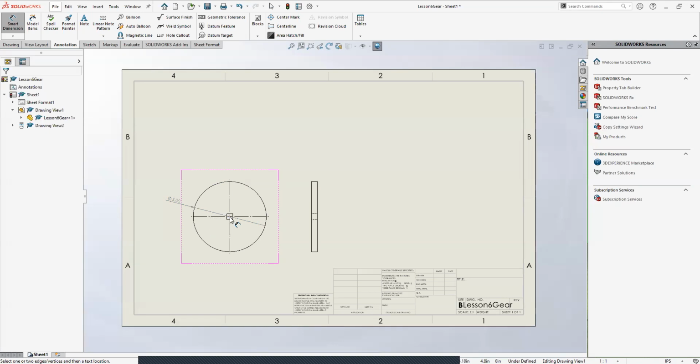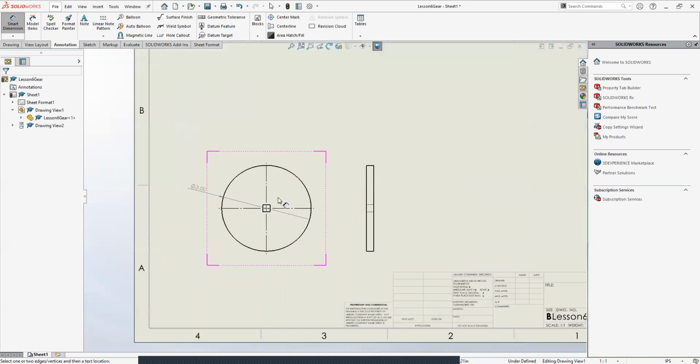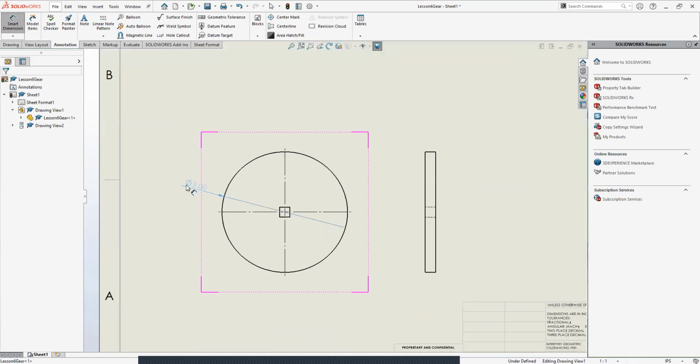Pretty much when you're doing these dimension lines, it's not super important their location. It's just important that it's clear, right? When you're adding more and more dimension lines, it can get kind of confusing. So it's often best to place them in ways where they're not getting mixed up with other dimension lines. Sometimes you'll be making a part that needs 20 dimensions. That's a bit much, but maybe even 10 dimensions. You need to be careful about where you're placing them so it's still easy to read.